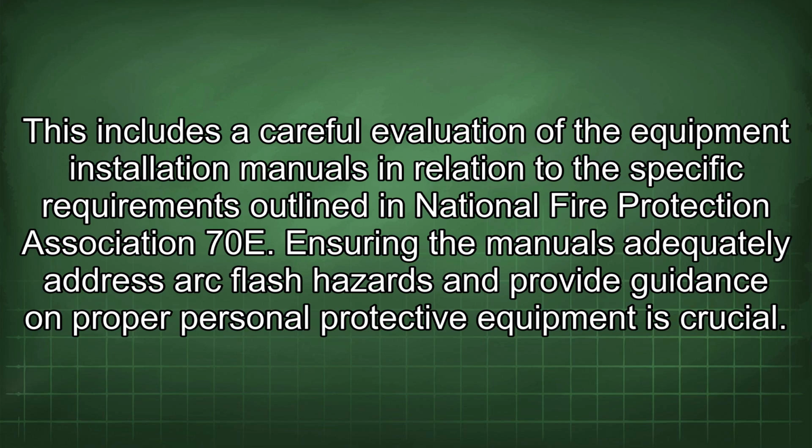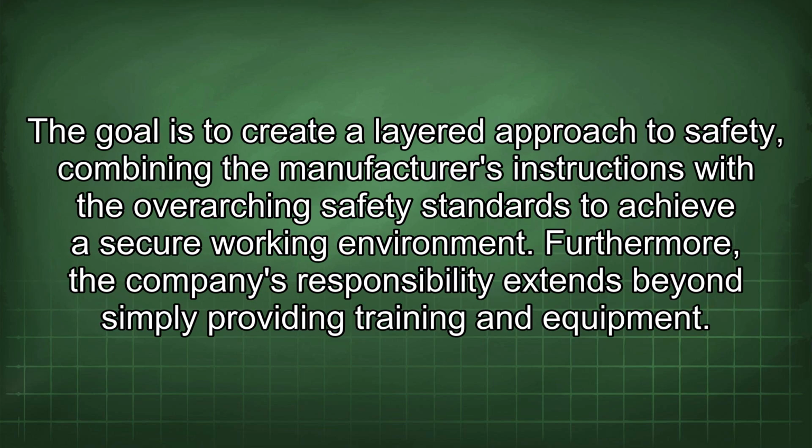This includes a careful evaluation of the equipment installation manuals in relation to the specific requirements outlined in National Fire Protection Association 70E. Ensuring the manuals adequately address arc flash hazards and provide guidance on proper personal protective equipment is crucial. The goal is to create a layered approach to safety, combining the manufacturer's instructions with the overarching safety standards to achieve a secure working environment.